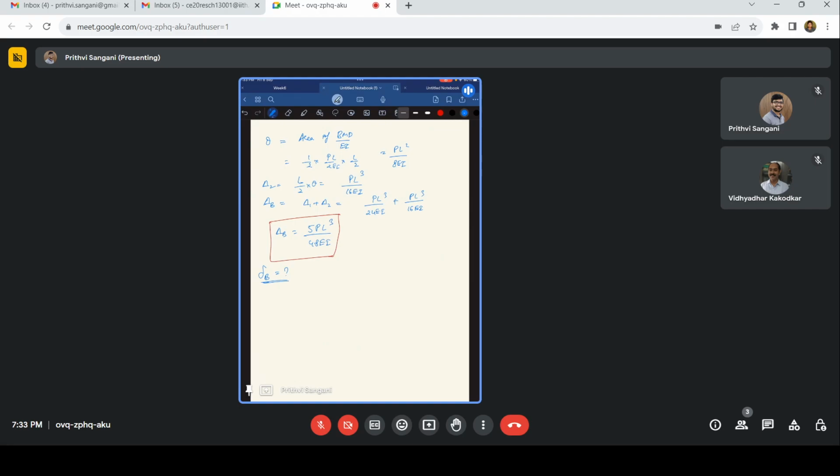You can find out the internal forces, the bending moments, the shear forces, the axial forces, etc. And once you have all those things, you can easily find out the displacement at each joint or each node. So that is the only added complexity compared to analyzing determinate structures. So this is one way of how to find out the unknown forces for the indeterminate structures.